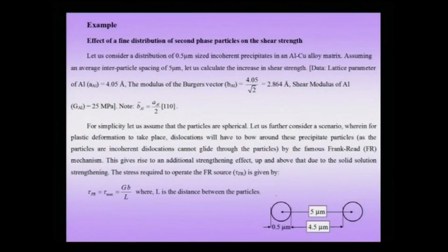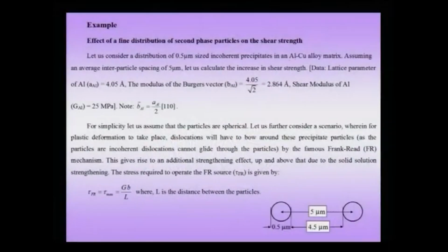Aluminum has an FCC lattice wherein an aluminum ion sits, and this kind of crystal typically is very ductile, but on the other hand is very weak, and therefore, it is not suitable directly as a structural application. Such a crystal can actually be strengthened by adding an alloying element, like in the case here you can make an aluminum copper solid solution, and this solid solution of copper and aluminum actually serves to strengthen the parent crystal.